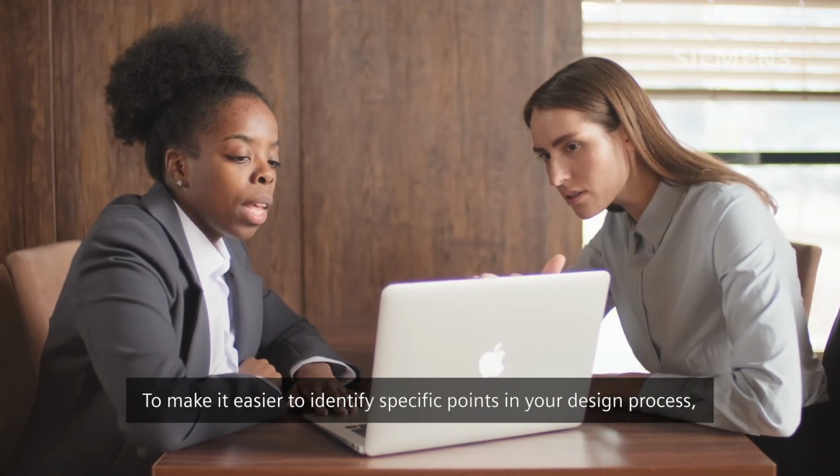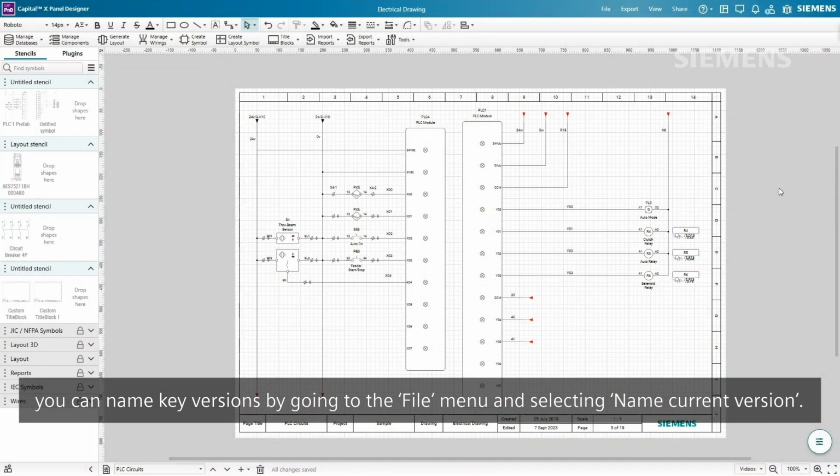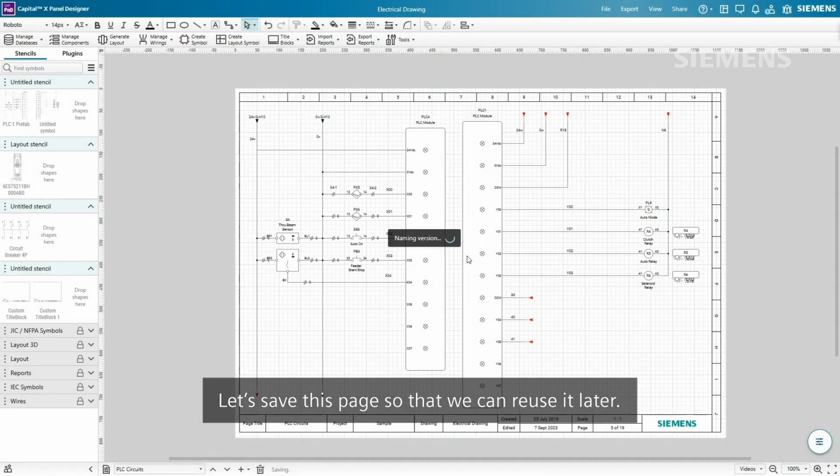To make it easier to identify specific points in your design process, you can name key versions by going to the File menu and selecting Name Current Version. This is especially useful for marking milestones or review stages, and we'll revisit this later when we demonstrate the version control feature. Let's save this page so that we can reuse it later.